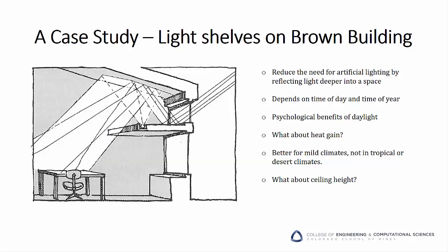It turns out these slats are actually called light shelves. They're a commonly used architectural technique that helps reduce the need for artificial lighting and regulate the heat gain of the room throughout the day. The shape and spacing of the horizontal elements is actually engineered to assist with energy savings in the building, and the design team likely wouldn't have thought to include these features from just looking at a topo map of the site. They needed more information about the influence of natural phenomenon and the local area to pull this off. That is where site analysis comes in.